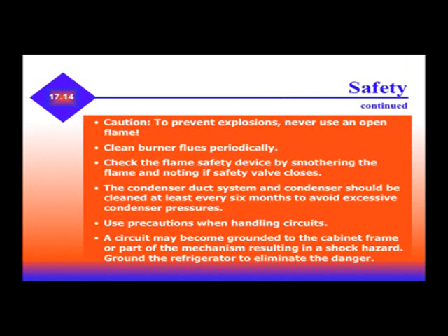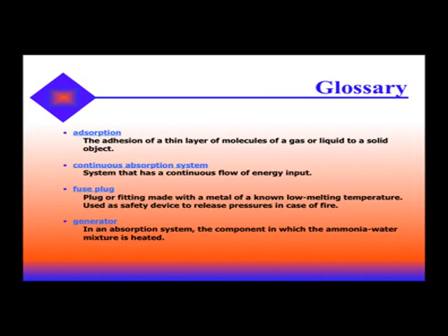Use precaution when handling circuits. A circuit may become grounded into the cabinet frame or part of the mechanism, resulting in a shock hazard. Ground the refrigerator to eliminate the danger.